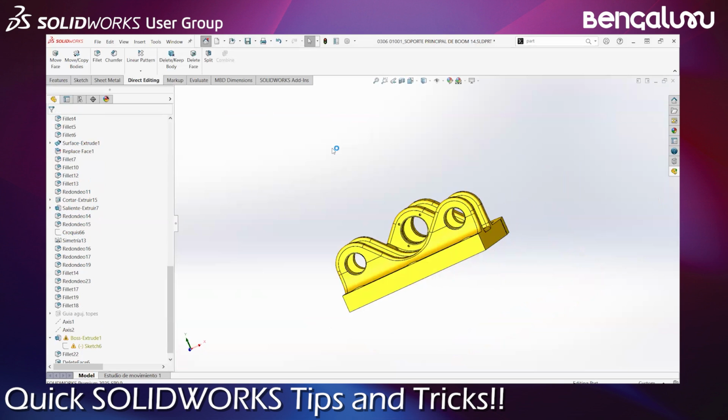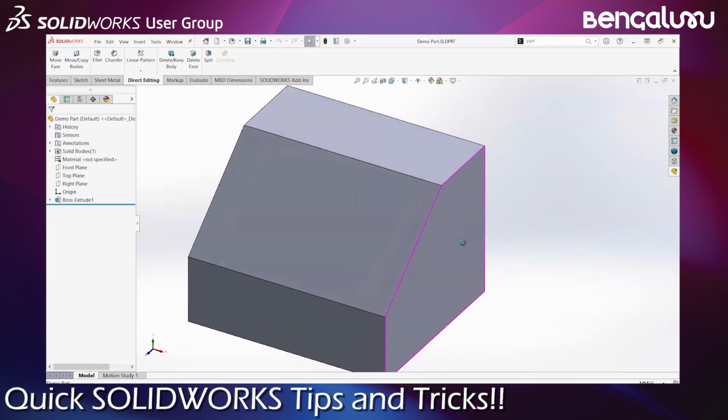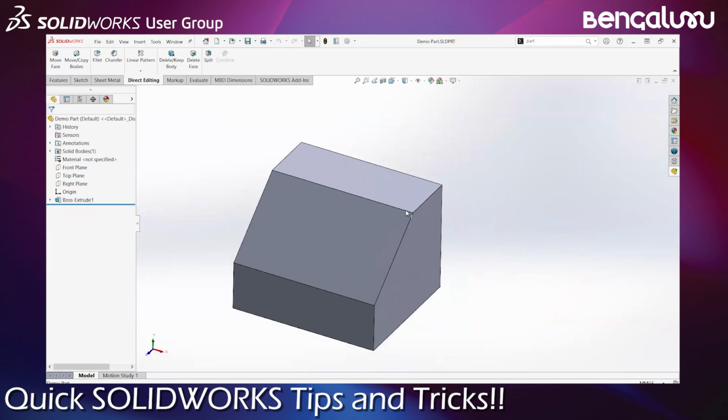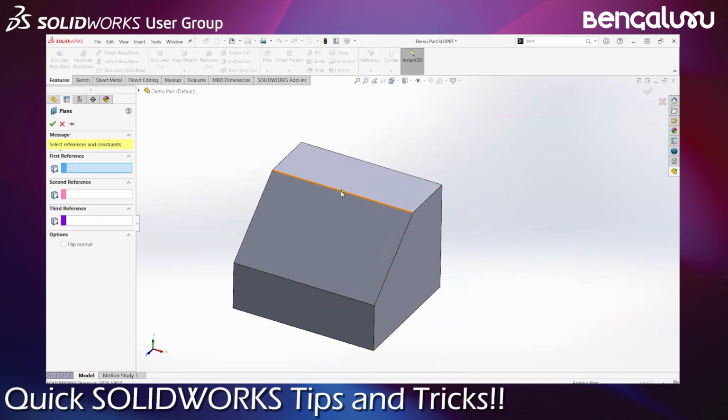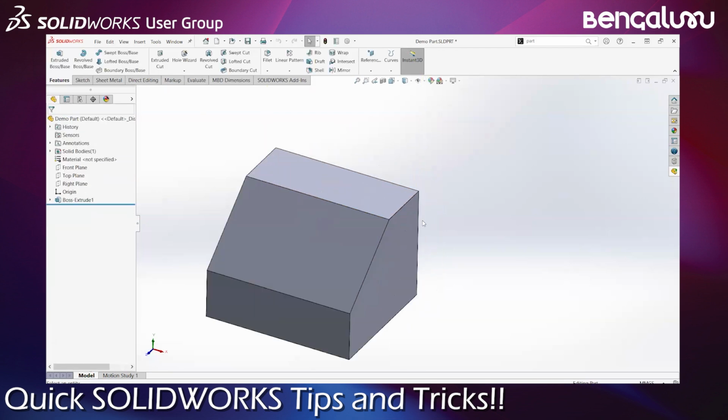I'll go back to one more example. Again, a very simple example. My intent here is to create a sketch exactly on this edge, on a plane that is perpendicular or parallel to that edge. The general workflow is: features, reference plane, select the edge, then you get a plane that is created, say okay, and then start sketching. But that's actually not necessary.